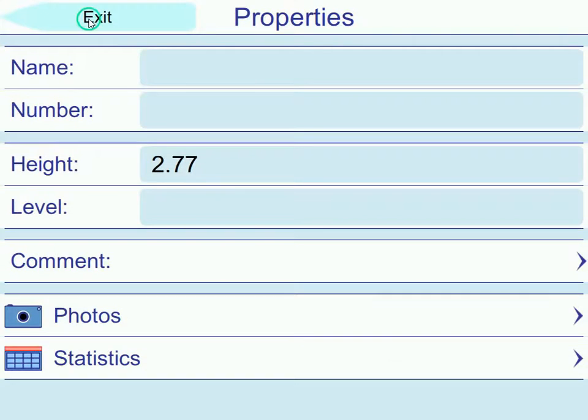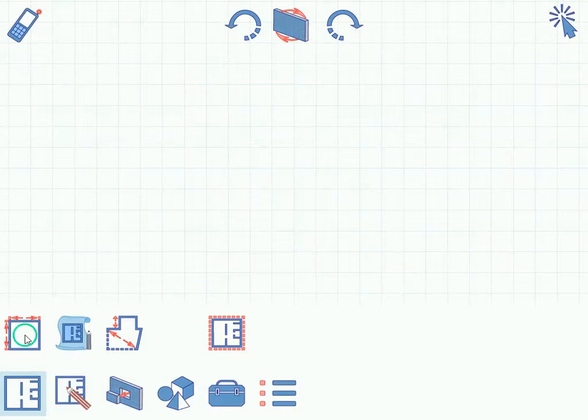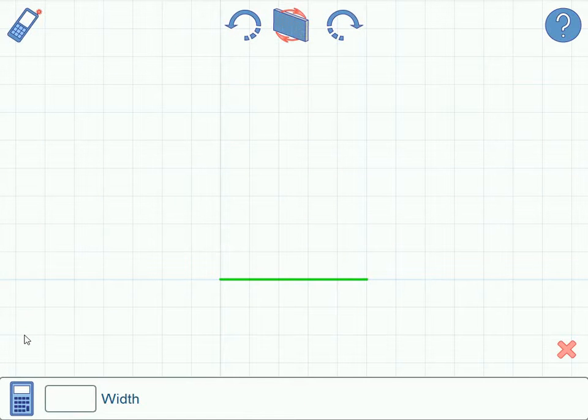Button operation in the toolbar. The first group of tools allows you to create new premises. This consists of 4 possibilities. Rectangular room creation, defined by width and length. Pattern-based room creation. This is the ideal way to create angular rooms. Step-by-step room creation. This is a flexible way to draw non-angular rooms. And external contour drawing. I'll show the basic drawing principles of the different tools with the rectangular room creation tool.